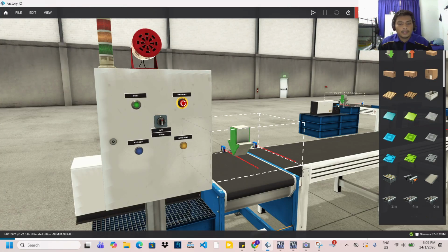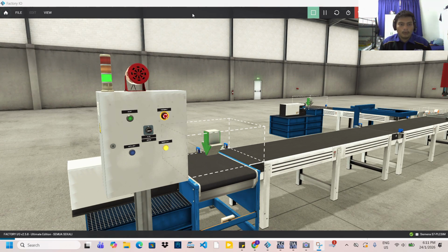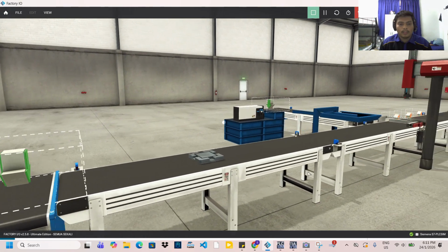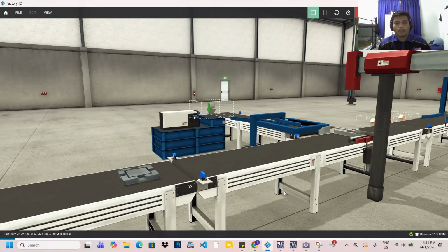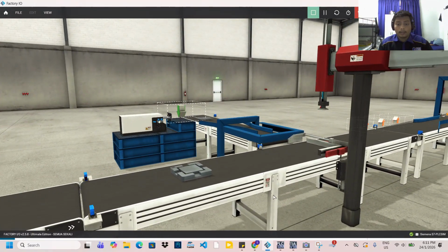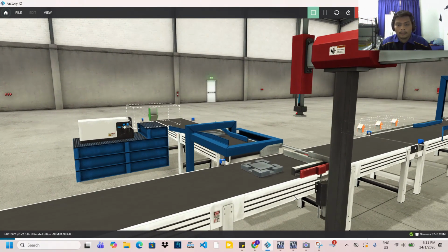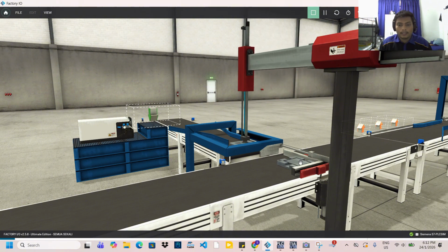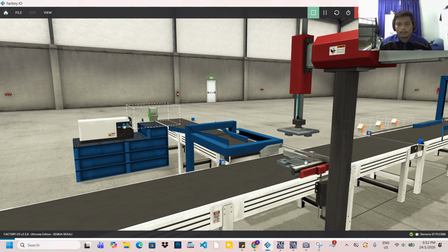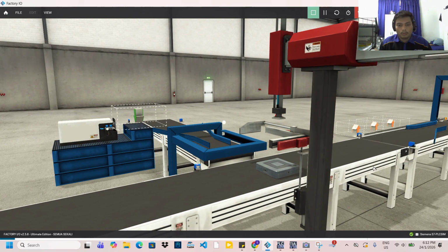Okay, we will open our Factory IO. So we turn on play. Now I will show you the manual mode with the metal object first. When the object is out of the distribution station, it will go into the joining station where the cap will be put on the base. Once this comes to the positioner, the sensor will make the clamp positioner clamp the base. Okay, and release. Perfect. And then the positioner will go up and let the object go.